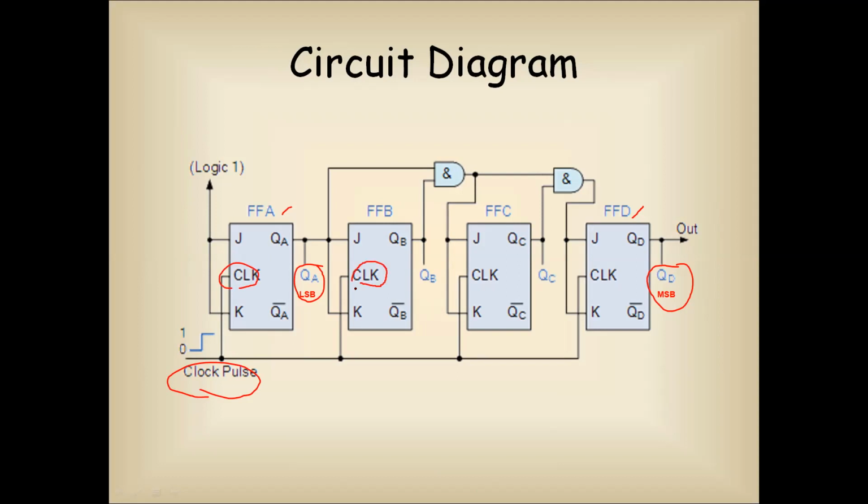That is why it is called a synchronous counter, because in an asynchronous counter, the output of the first flip-flop is given as the input clock signal to the next flip-flop. Whereas here, the same clock signal is connected to all the flip-flops. So that is why it is called a synchronous counter.